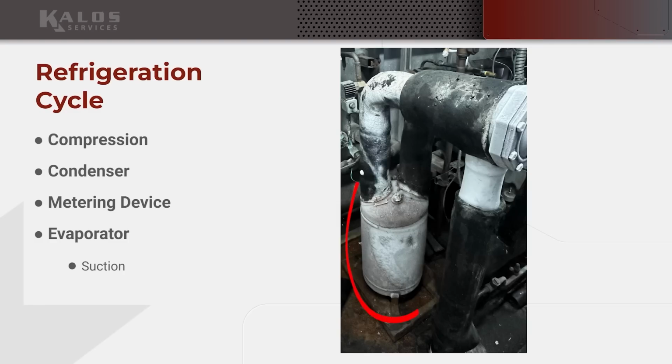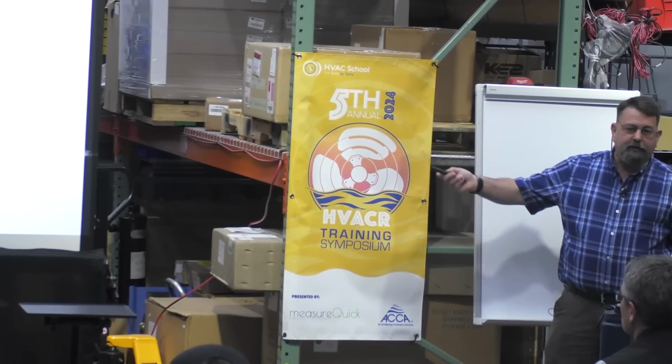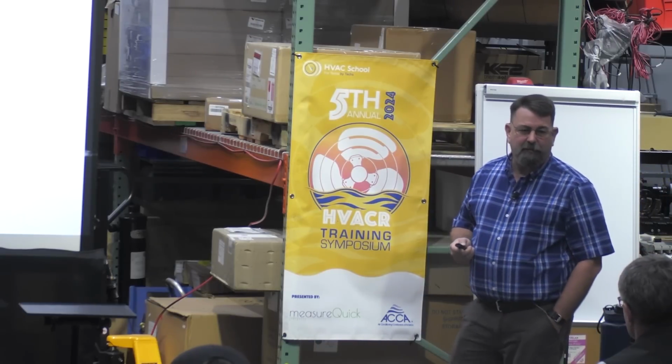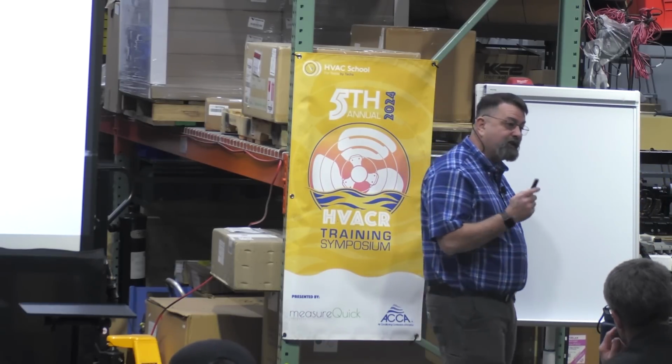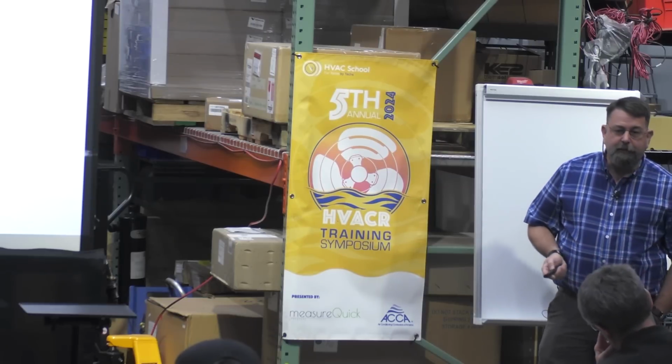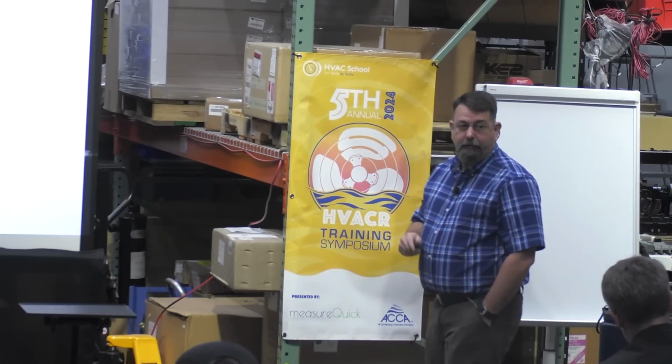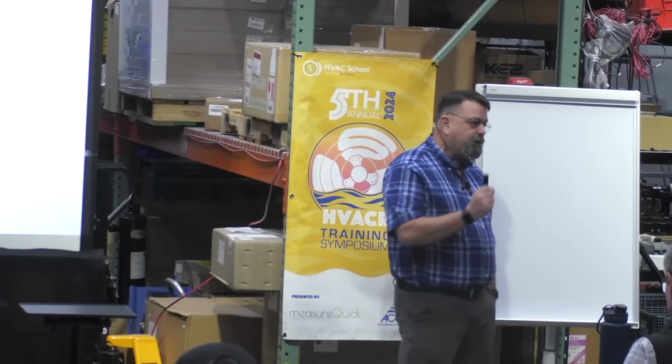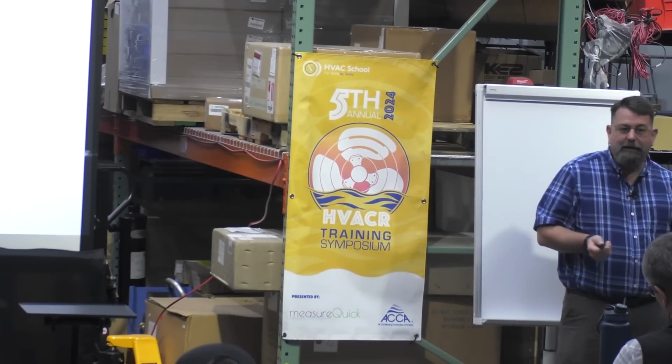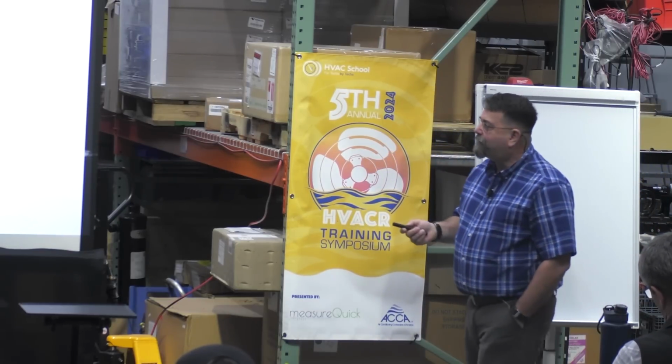Now, I've got a suction accumulator. All right, might see that in air conditioning sometimes, right? This is a little bit of our flood protection, is the idea. You saw that evaporator fan was missing. I had a piece of cardboard covering the hole. Well, you think that may be flooding a little bit? Yeah, it might be, because I'm not bringing as much heat as that valve is set to control. It's way less. So that valve may not be able to control that, especially that mechanical valve. You know, it's going to close down to its extreme and may not be enough, right? My electronic valve does a lot better at that.